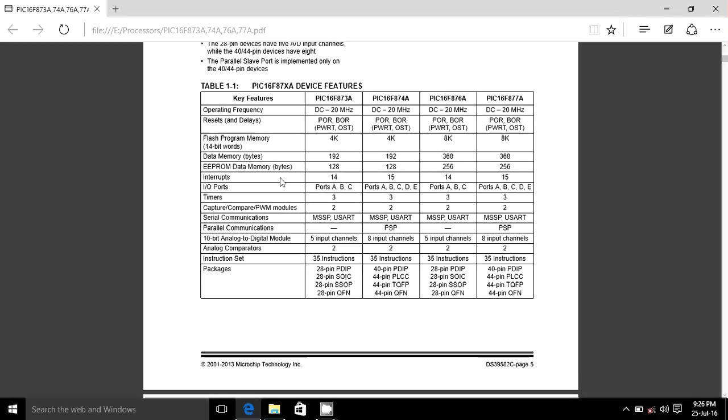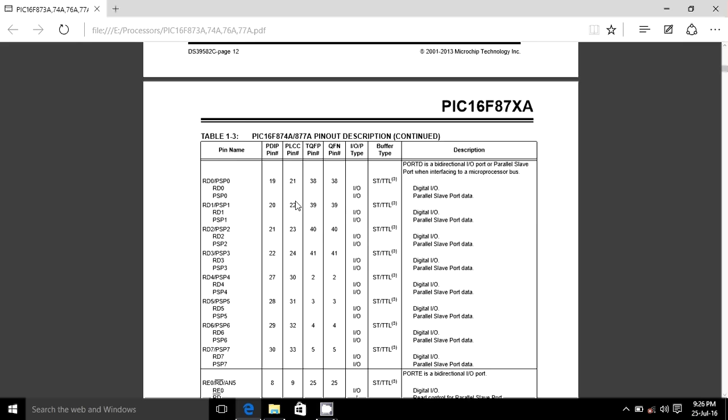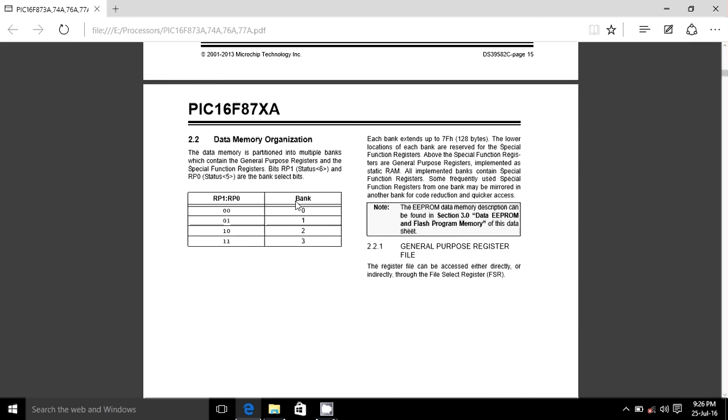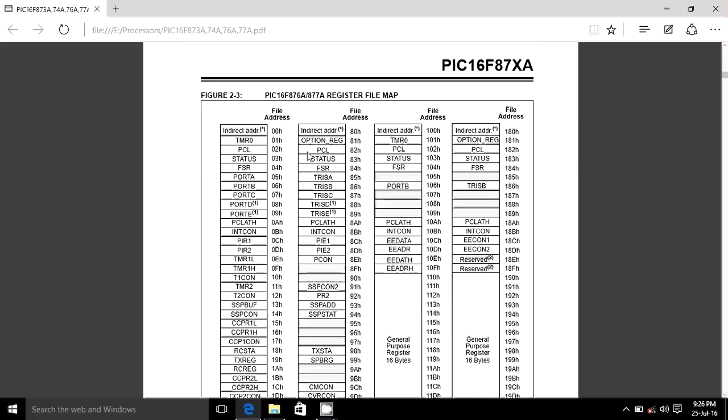Timer interrupts. Here it is. We are using the PIC16F877A processor. So 14 types of interrupts are there. You go through it and study it: memory, how to enable the timers. These all are memory maps. These registers are located in memories. Like if I access port B, then I use the 06 hex address file.